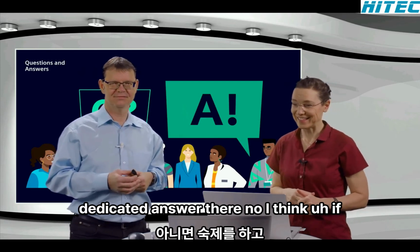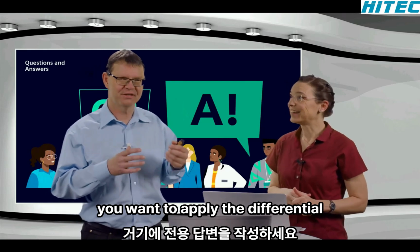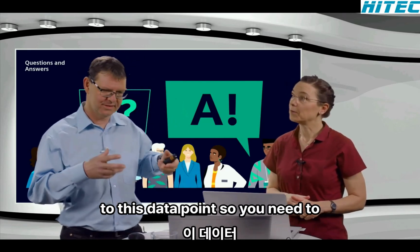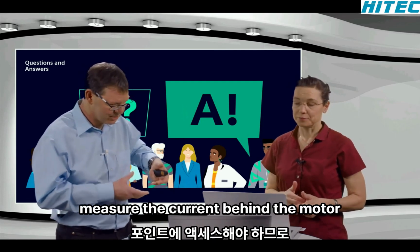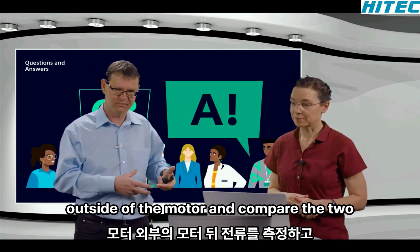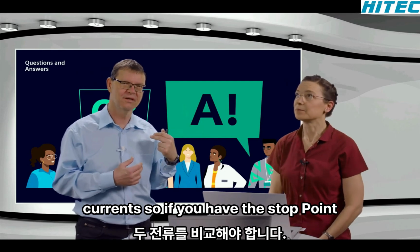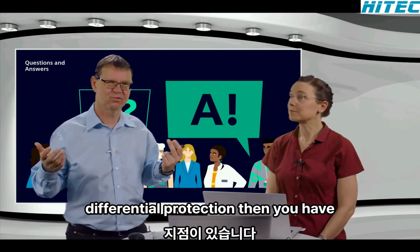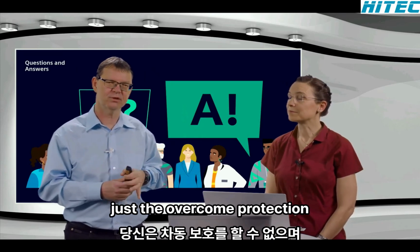I think if you want to apply the differential protection, then you need to have access to the star point. So you need to measure the current behind the motor, outside of the motor, and compare the two currents. So if you have the star point somehow in the motor, you cannot make the differential protection. Then you have just the overcurrent protection.